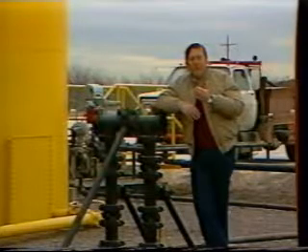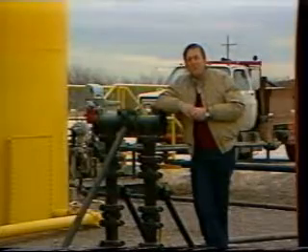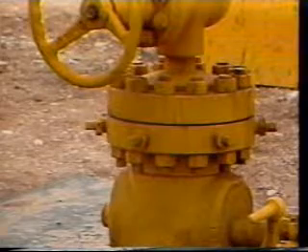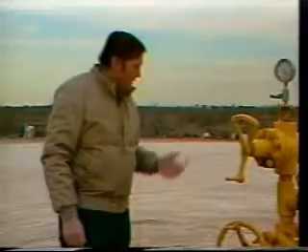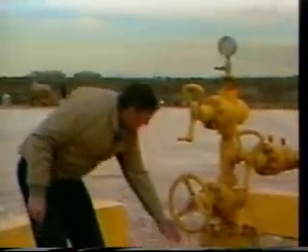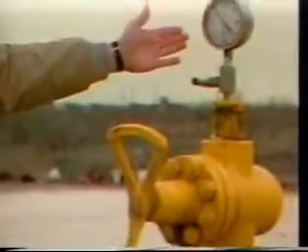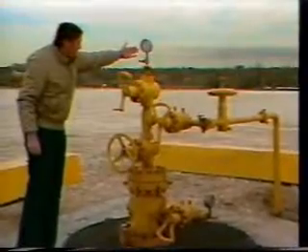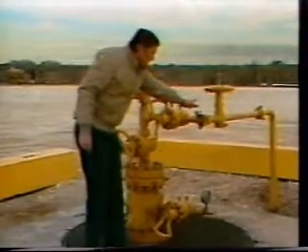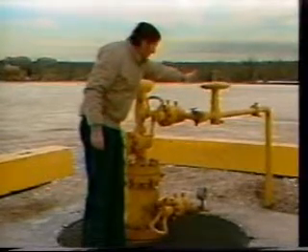Let's see how the oil and gas are produced from the producing wells surrounding this production facility. Here we have one of the producing wells that produces oil and gas to the tank battery. In this case, it's a flowing well. You see that the tubing comes up through the center of the wellhead here. Its pressure, about 1,000 pounds, is measured with this gauge. The production then comes out through this orifice and onto the production battery.